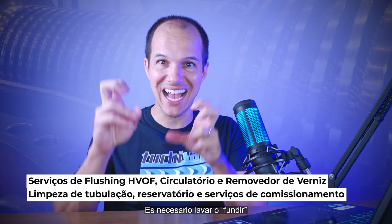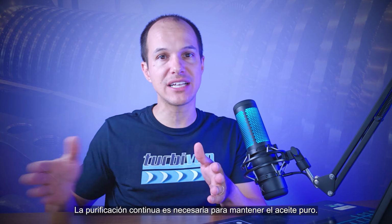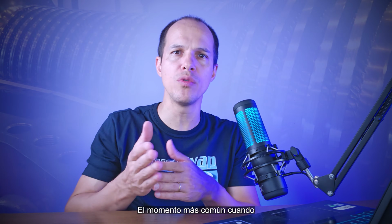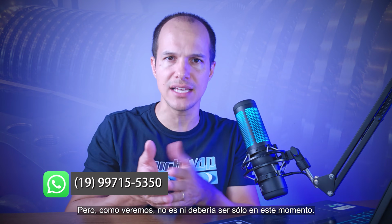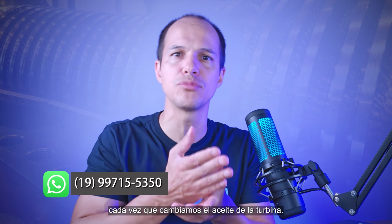How will contaminants from these processes be removed? It is necessary to wash or flush and purify the system to remove them before the turbine starts. Continuous purification is necessary to keep the oil pure during operation, unless there is a catastrophic failure. The most common time when turbine maintainers perform flushing is between oil changes.